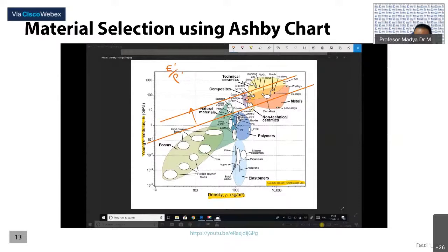And in fact, the only other materials are ceramics. Now there's a number of different problems with ceramics. They're difficult to form, but they're also relatively brittle. So once again, if we're trying to optimize the design of our bike frame, we're only really left with one possible material, and that's the composite material, carbon fibre reinforced polymer.